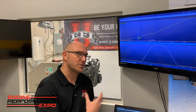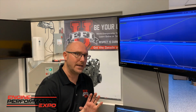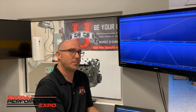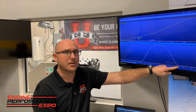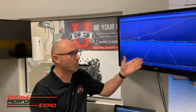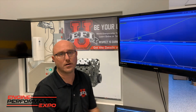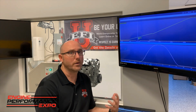So as the electric motor now is spinning all of the parts in the valve train, we can take a laser and stick it in there, and that laser can point straight up and watch the valve. That's where we get this plot here from an actual electronic measurement of how the valve is opening and closing and how fast and how far. And that allows us to really start taking data-driven decision approaches to what we're going to do in the valve train.